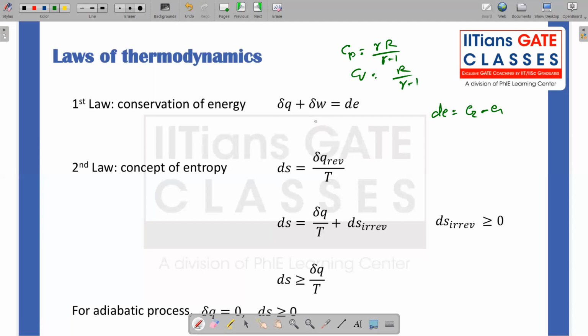So that is why I cannot write in this form like dq is equal to q2 minus q1. That is not correct. So I have to integrate over the path, and I have to get the exact value of the path, the heat transfer or the work done. So that is why we usually denote it using delta q and delta w. That is the notation we use for path function variables, right?